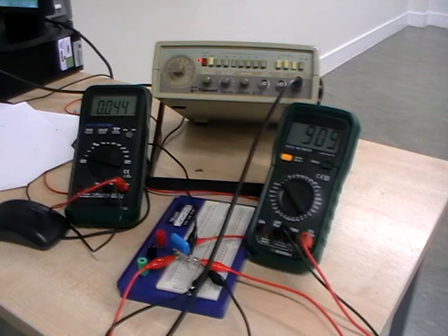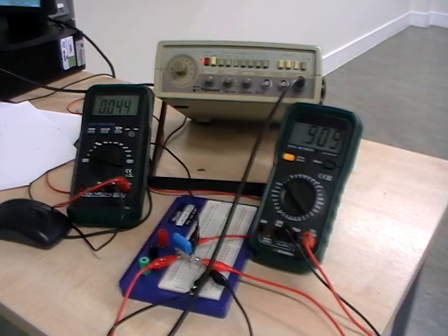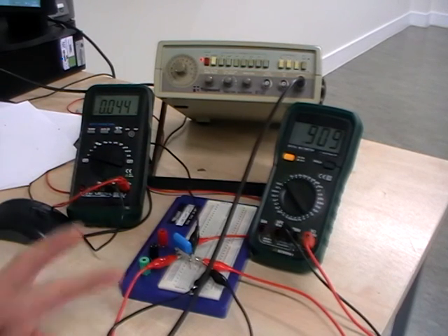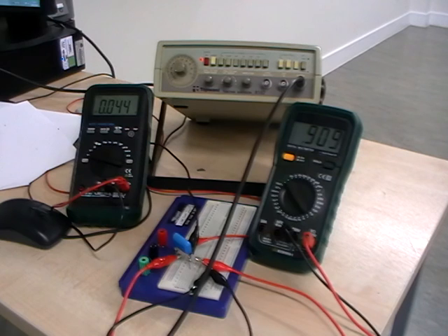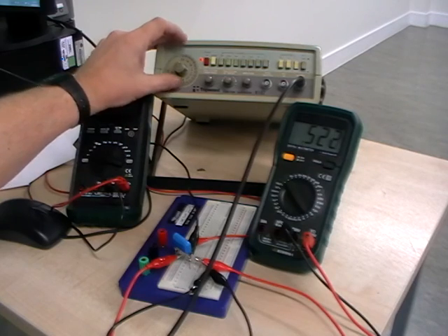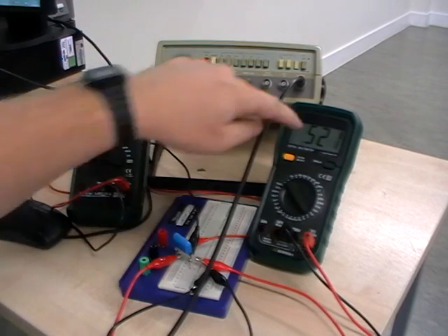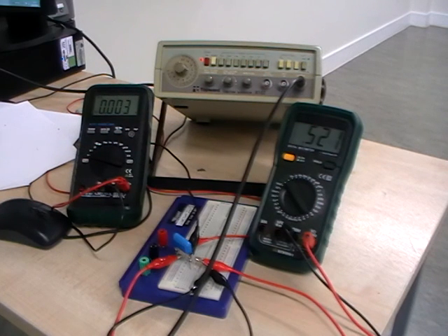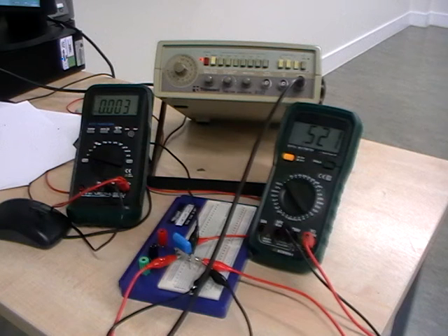Before, when we started off, it was almost like an insulator where it dropped the complete voltage, meaning that the resistance was so high that my resistor wasn't hardly dropping anything, but the capacitor was dropping it all. Okay, we're going to go really, really crazy and go up to about 20 kilohertz. And again, when I look at the ratio now, we've got about half a volt across our resistor, and only about 3 millivolts across our capacitor. So you can see what's happening here is going more and more extreme.